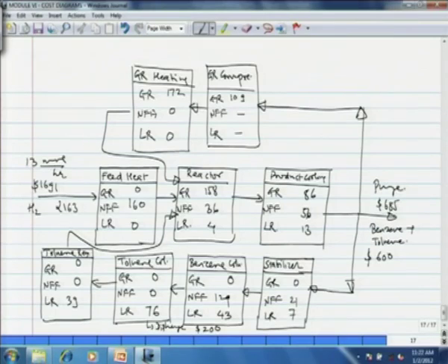Now, this cost allocation diagram is a very handy tool of assessing the process alternatives. Now, what are the process alternatives that we can see? The first process alternative is to recycle diphenyl. Diphenyl is a reversible byproduct. So, you can see there is a tremendous loss of toluene in the form of diphenyl. If you see the annual loss, it is over $1 million.